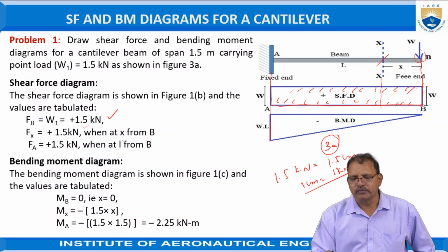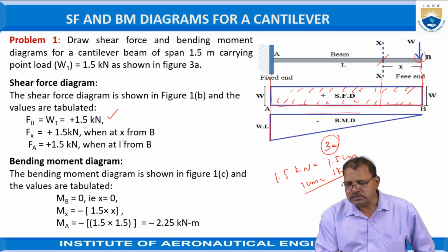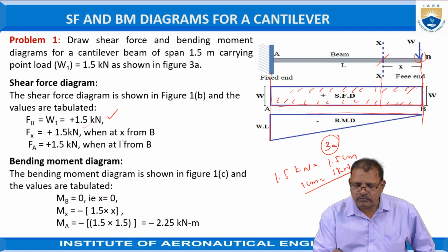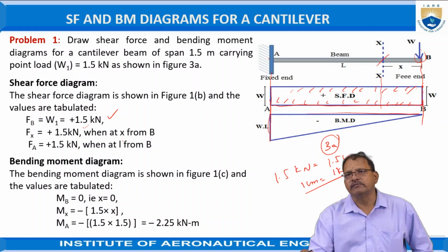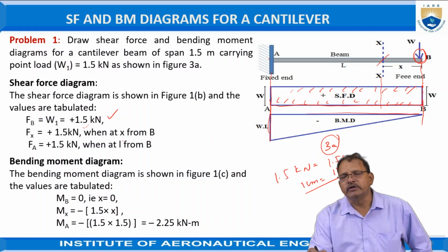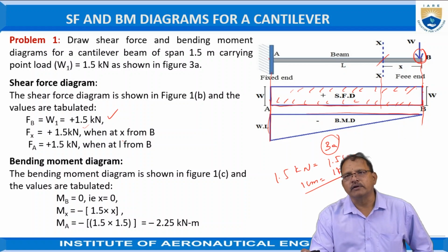See now. Again, draw the horizontal line to represent the length of the beam, and draw only vertical lines from the various sections of the beam. Now the effect of the bending moment of this point load is that it will deflect the beam in the form of an inverted V shape, that is called hogging effect. Hence it is treated as a negative bending moment.